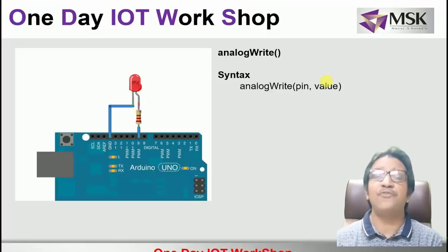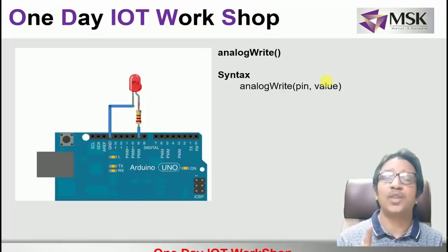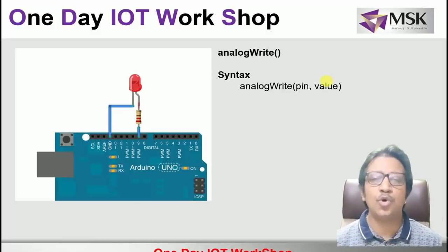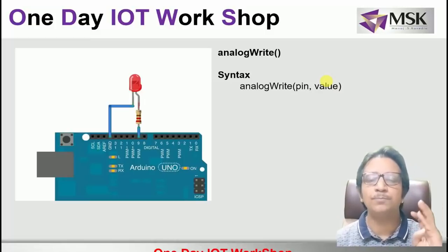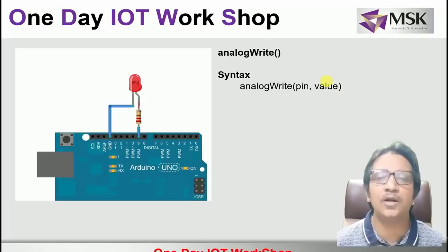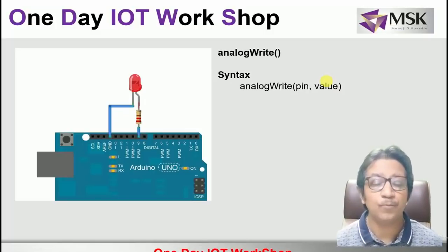But again, there is a condition for analogWrite: only pin numbers 3, 5, 6, 9, 10, 11 can be used. I hope the functions pinMode, digitalRead, digitalWrite, analogRead, and analogWrite are clear to you. So we'll move further.